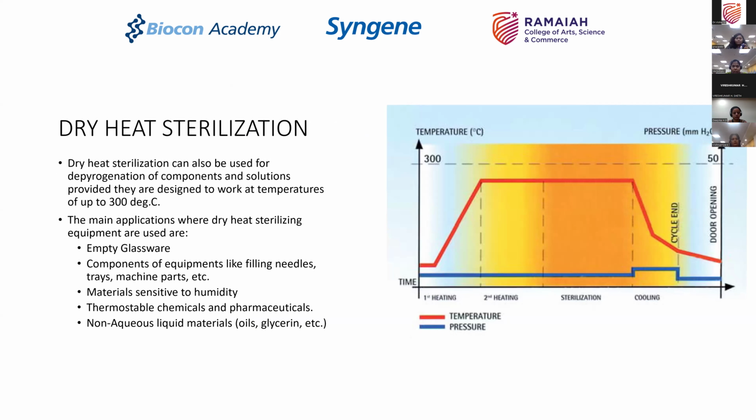In case of a tunnel, when you are feeding it from a washer, you preheat it with the exhaust air, so the temperature of the component starts to already reach a higher value, and then you increase the temperature all the way to 250, 270, 300 degrees centigrade. After you reach that, you hold it for the minimal time required, and then you subject it to cooling, and then you take it out and subject it to fill finish operations.